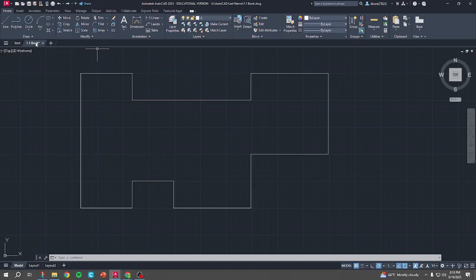Circle. The next thing is it shows you two different types of circles. Diameter circles, which is up here, and this midpoint tracking thing. Look what happens. I have a circle tool selected, and then I'm going over the midpoint of this line and the midpoint of this line. And now if I go back down to the two midpoint intersections here, I can click, drag, and it places that circle perfectly for me. Just type in 60, done.